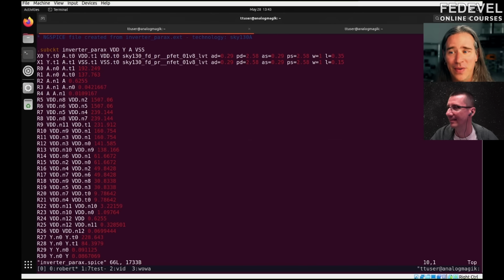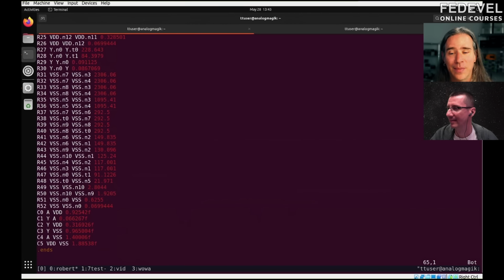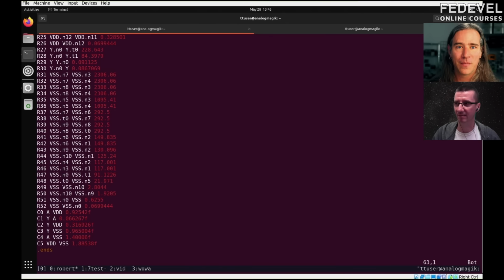So there's our 2 MOSFETs, and now resistances, and some capacitance. We even go up to a whole femtofarad between a couple of these things. Okay, so now this is basically the physical circuit. This is not the theory, this is the real circuit. As close as we can get, yeah, this is the real thing. These resistances, some of them are really tiny, some of them are not. Some of them don't matter, some of them do. Can you simulate this? Yes.